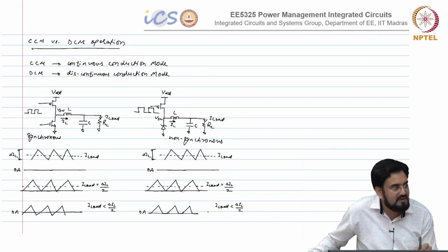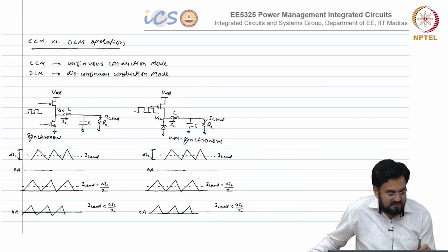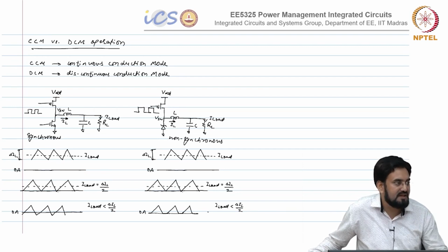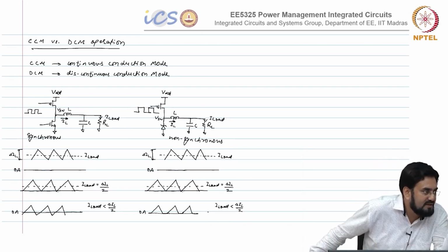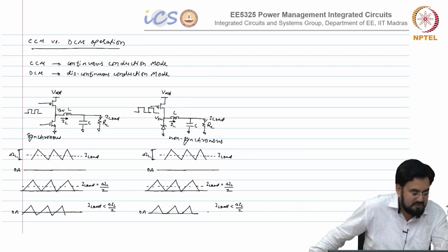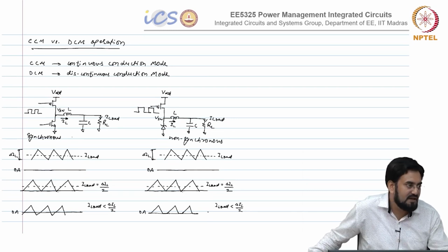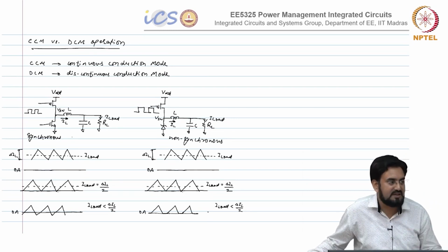So, that will behave like a diode with a 0 forward voltage, because what you are looking, so you know, when the reverse current is there, this VSW node will go positive. So, if the current is flowing in this direction, then this voltage is negative VSW. The moment current gets reversed, this will try to go positive. So, all you have to do, look at the 0 crossing point. So, when it goes from negative to positive, you turn off this MOSFET, and it will behave like an ideal diode, and that is what you do actually to enter into discontinuous.